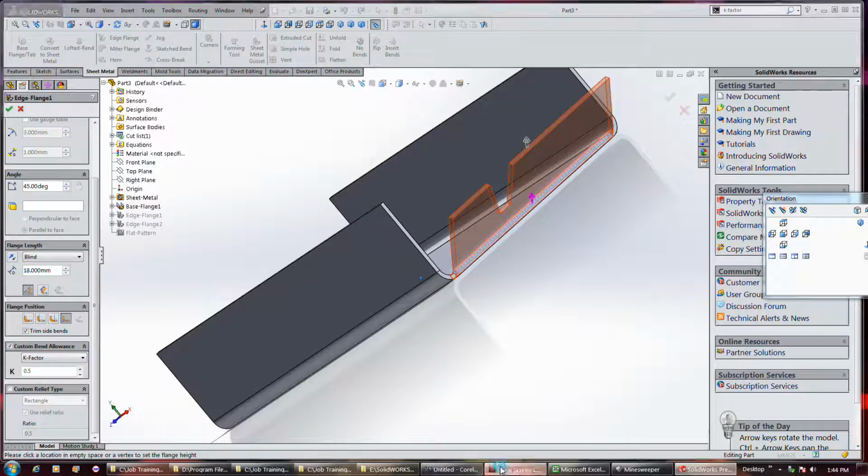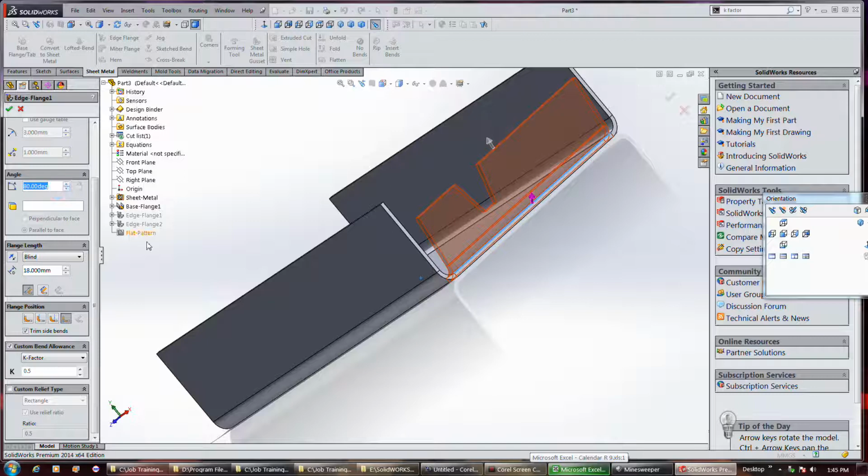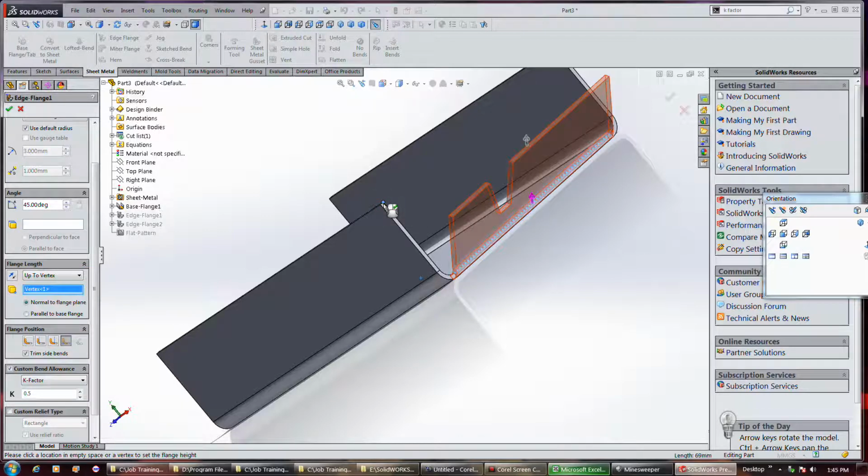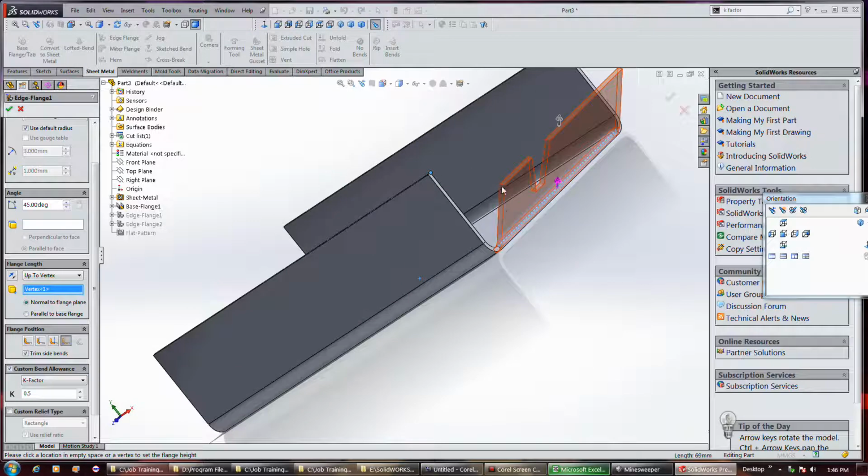Yeah, hold on. By the way, if this is selected, you can use your mouse scroll wheel to change the angle. But like I said, here's where I had put the offset, but you can't select it anymore. One thing I can still do though is go link to vertex, so I can click that, but it's just going to make it parallel to that, as a projection.